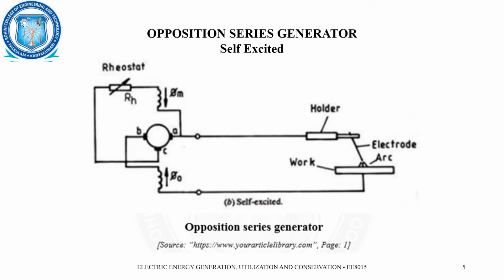lower the generator voltage, as the EMF induced in the armature winding of the generator depends upon the resultant magnetic field. At the time of short circuit, phi m and phi naught are nearly equal and opposite in action, and hence we know the resultant flux is negligible as well as the terminal voltage will drop to zero.